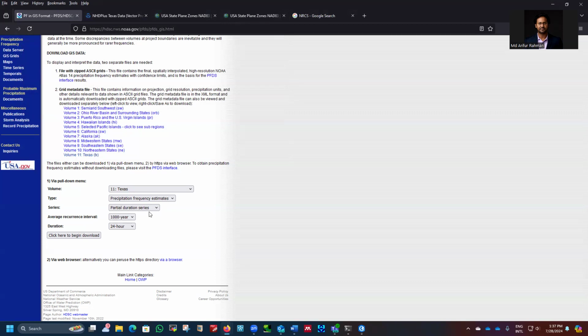So other than these profiles, we need to even generate 2 other profiles. We call them 1% plus and 1% minus. Meaning if you have 100-year return period, we call it 1% chance of occurring in a year. So we need to just generate 2 other profiles based on a different method we have. So we need to calculate 90% plus, like upper 90%, lower 90%.